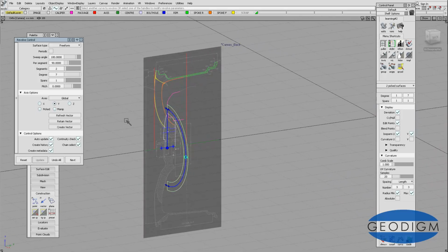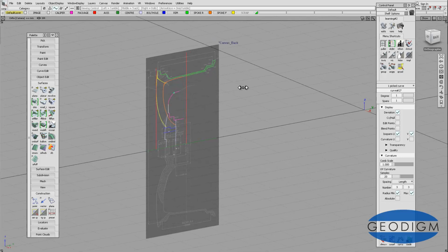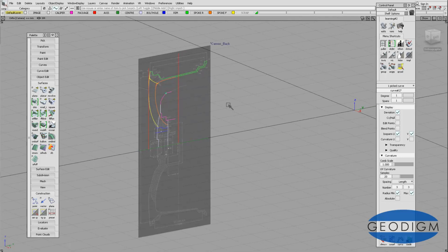The only thing is that in general we don't want to pick global, we want local, in that we are often wanting a point of rotation that we're controlling rather than the system. So what we could do is go and pick that curve there, and the reason why it was revolving up that way and not down the way we expected was because the pivot point is up here. So what we need to do is move that pivot point.